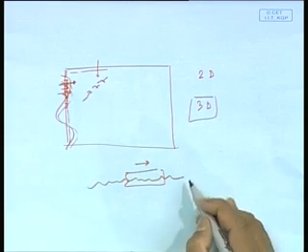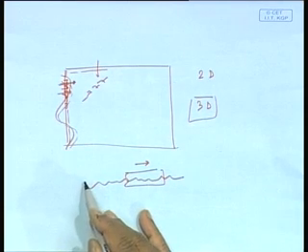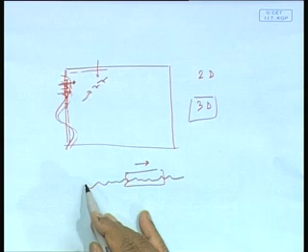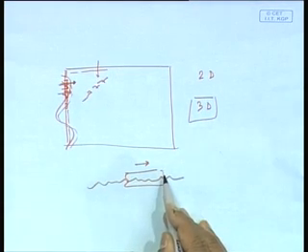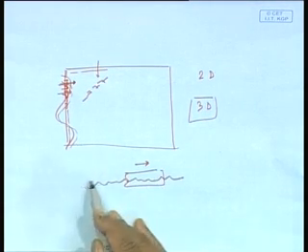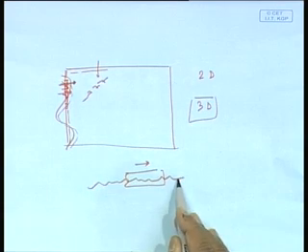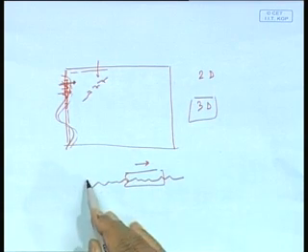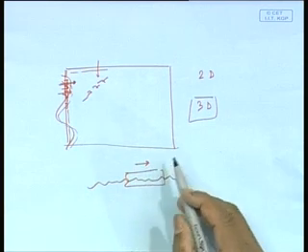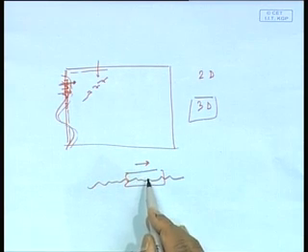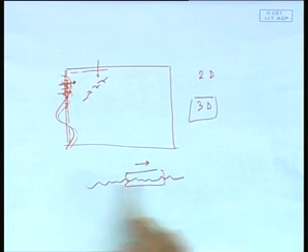Take an extreme example, a single wave. Suppose the whole thing is modeled by one wave of 5 meter height. In the 2D case there is a wave of 5 meter height coming from this side. In the 3D case I say there is a wave of 4 meter height from this side and 1 meter height from the other side. Now this body responds mostly to waves in this direction.